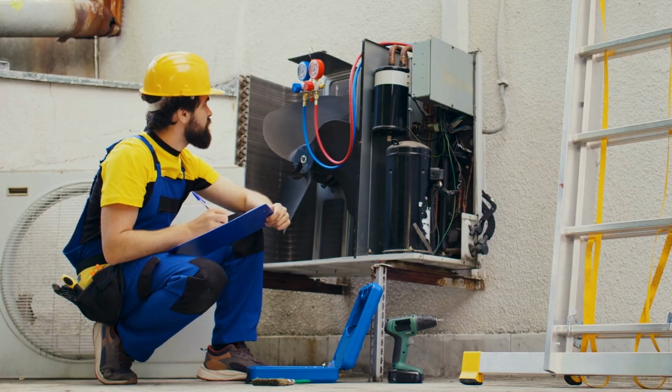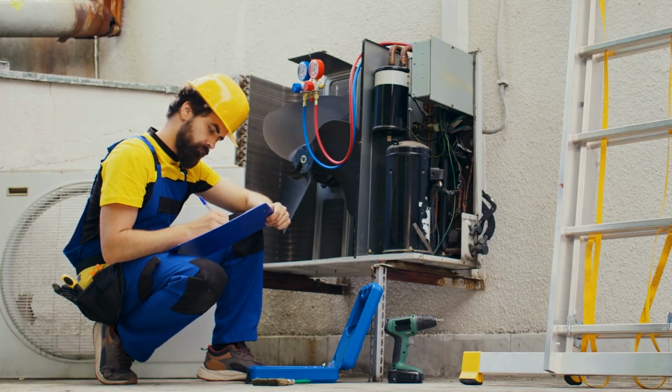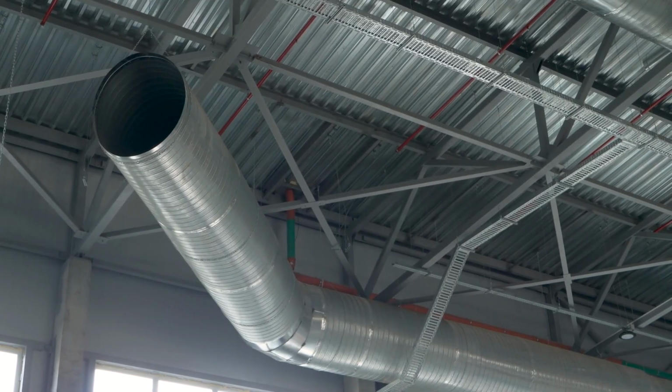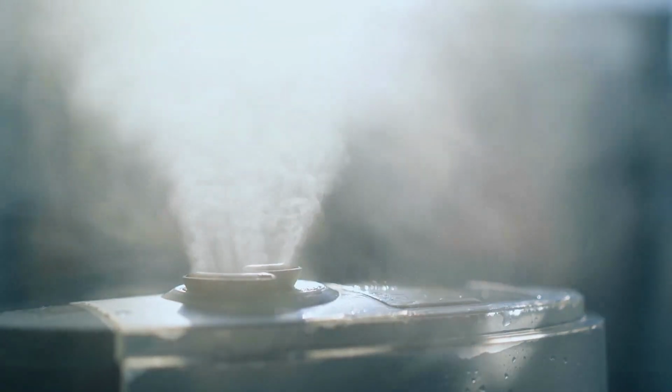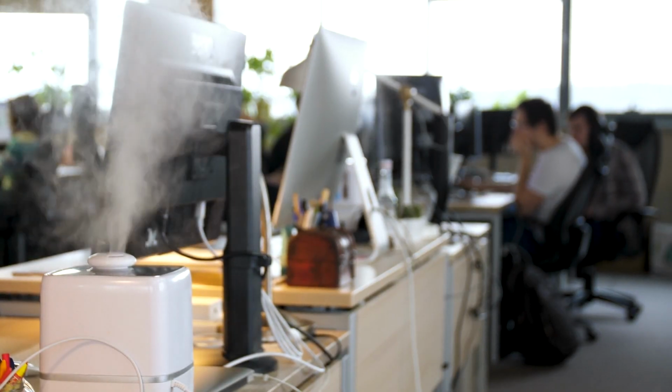between 30% and 60%. Making sure that air conditioning and heating units are in proper working order is essential in keeping the temperature in the right range. Using humidifiers and dehumidifiers helps increase and decrease the relative humidity appropriately. They should also make sure routine maintenance of all ventilation systems is done and monitor carbon dioxide levels.